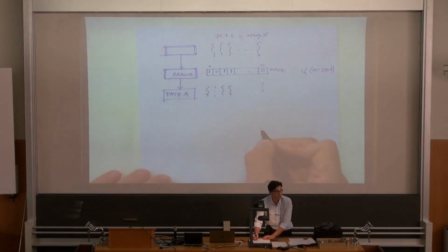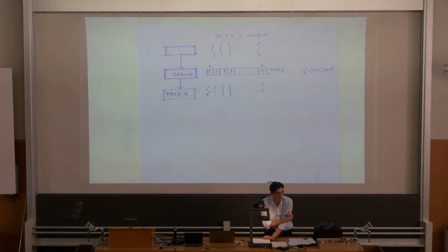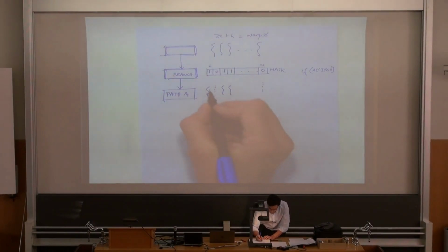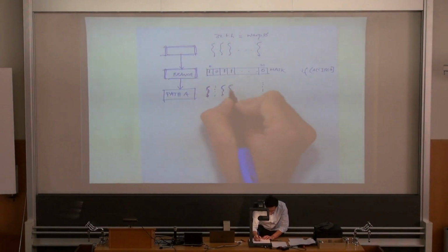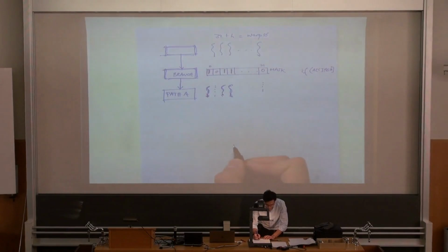Maybe the other ones are also executing, but recall the simple implementation of the mask: they won't be committing the final result to the corresponding output register, right? So the actual execution is only for these threads for which the mask is equal to 1.